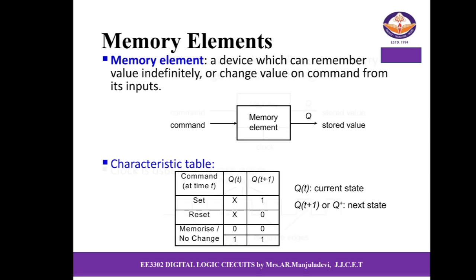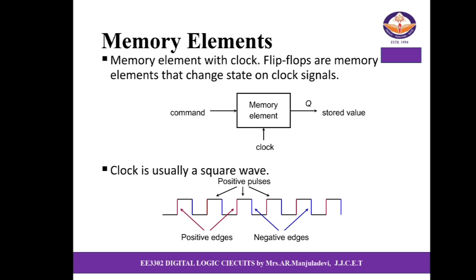A memory element with a clock is known as a flip-flop. Flip-flops are memory elements that change states on clock signals. This is the logic diagram of a flip-flop. The logic diagram is the same as the memory element, only the clock signal is added to the memory element. This is the timing diagram of this memory element. The rising edge is known as the positive edge. The falling edge is known as the negative edge.